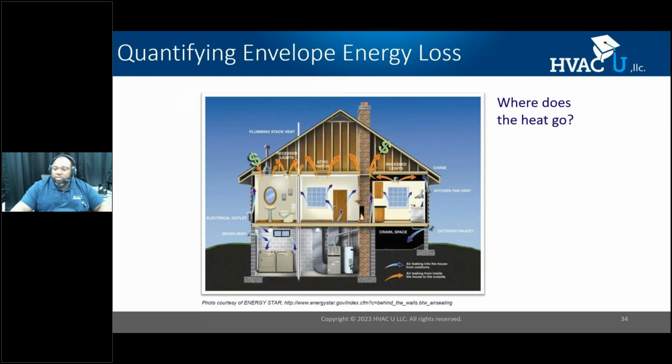So I paid the utility costs to heat up that air, and as that air gets heated up and it migrates up, if it leaks out the building shell, guess what? Air has to leak in. Now that air that leaks in, guess what? It's not conditioned, it's not clean, it's not humidified, it's not filtered. We have to pay to get the air to the required comfort levels so that the building occupants are satisfied. So this is a vicious cycle. And what we learn, the older the building is, the more air leakage issues we have.